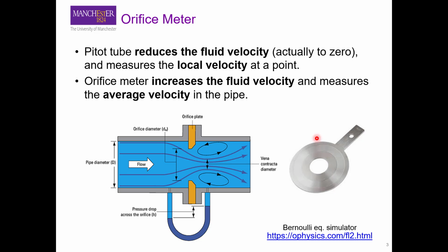Previously, we discussed pitot tube. In contrast with pitot tube, which slows the fluid and measures the resulting increase in pressure, orifice and Venturi meters cause the fluid to flow through a restriction in order to increase the flow velocity and measure the resulting decrease in pressure.